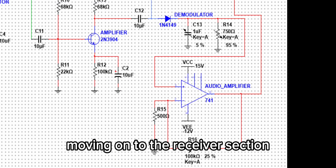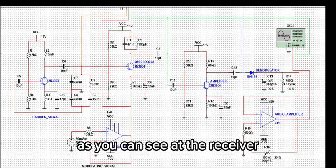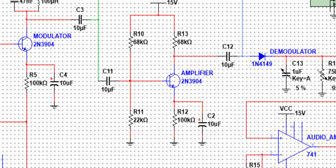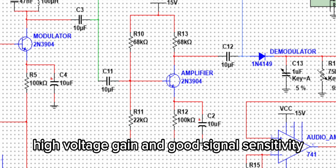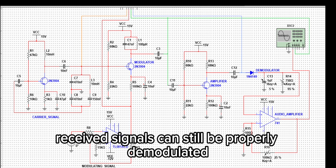Moving on to the receiver section, for the RF amplifier, we have the common emitter amplifier. As you can see, at the receiver, the first block is an RF amplifier, which boosts the incoming AM signal. This is a common emitter amplifier, chosen because it provides high voltage gain and good signal sensitivity. This stage ensures that weak received signals can still be properly demodulated.